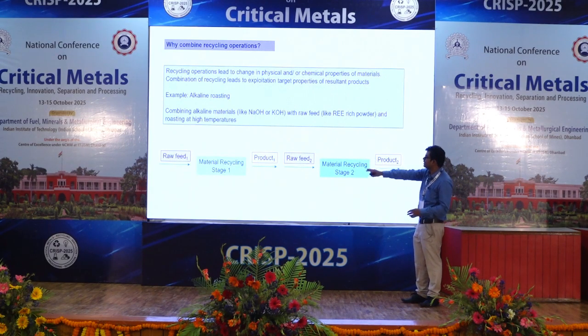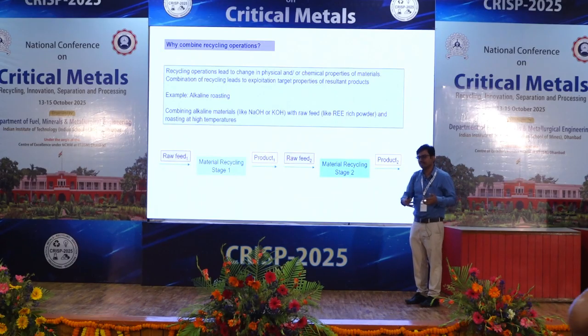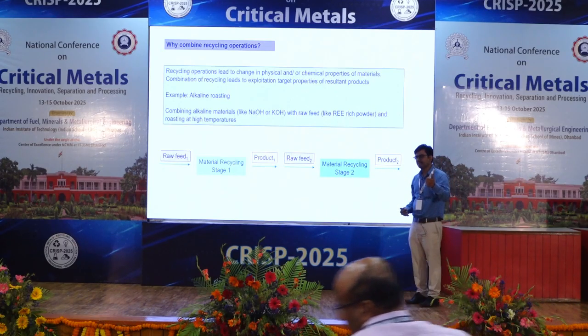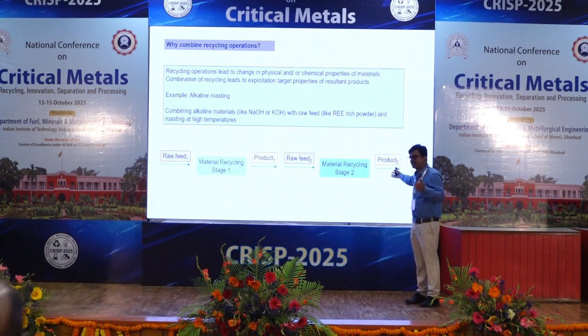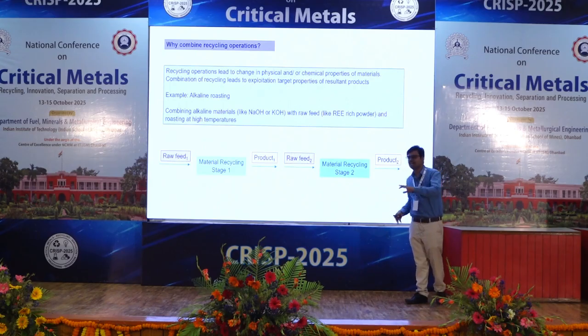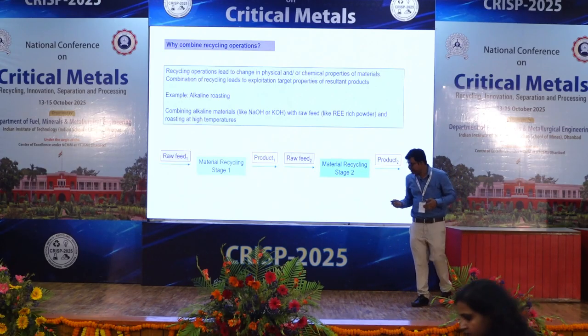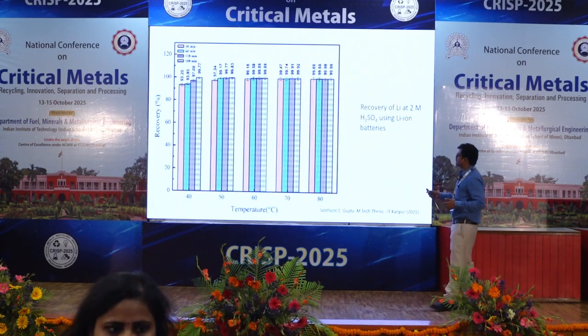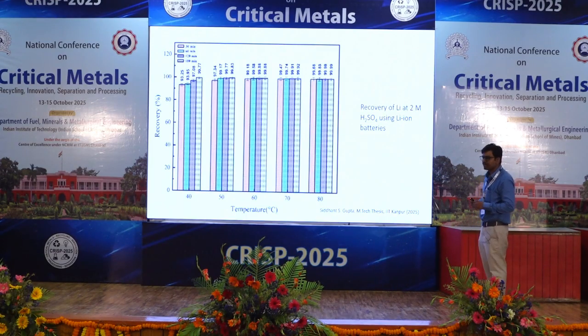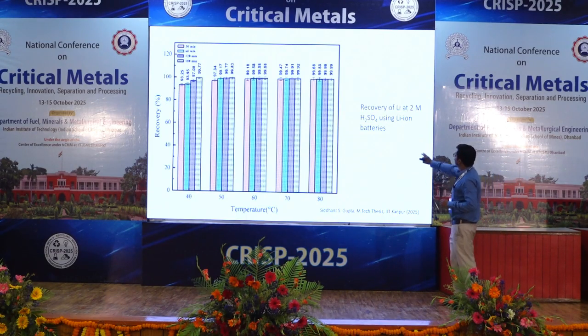So raw feed is something that we start with, and in this case, something that I'll be discussing is lithium-ion batteries. So we start with lithium-ion batteries and Co types. We first perform the discharging, dismantling, and then we get the black mass, and with the black mass we go for the actual recycling through hydrometallurgy. This is something that has been performed by one of my students, Siddhant, which is basically